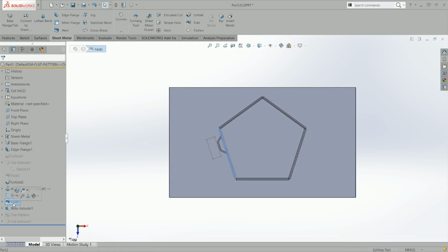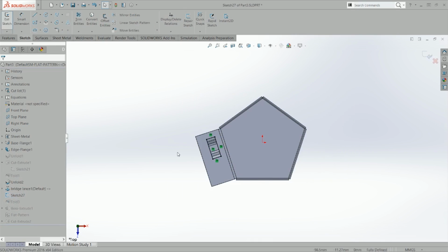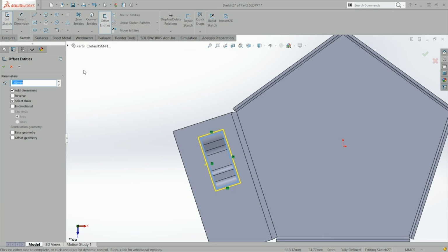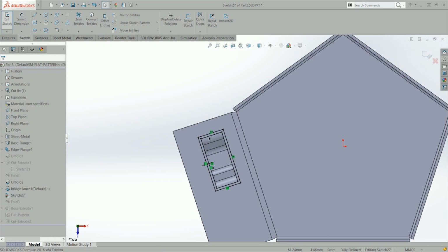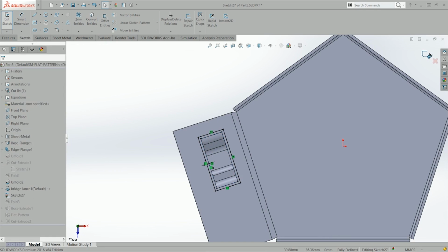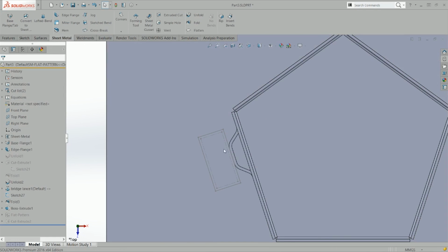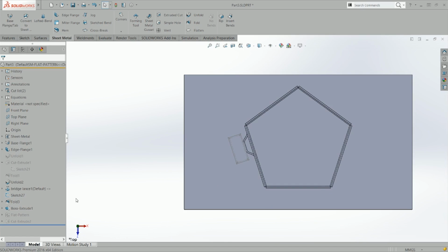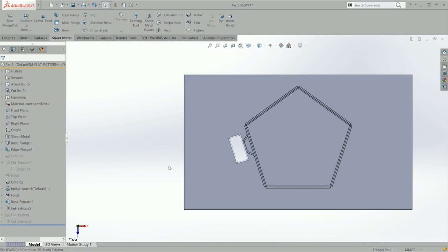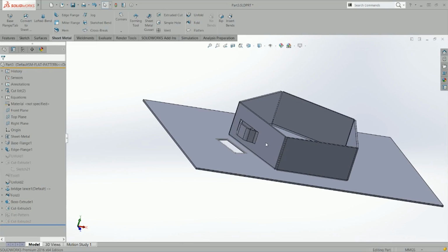So I'm gonna use this sketch, and then right-click it, edit it, and just make an offset of 1 mil. Select the chain, make it for construction, so we still get the same position. It's just offset. So once we do that, I'm gonna make a cut, and there you go. So now let's say you had a finger fault here.